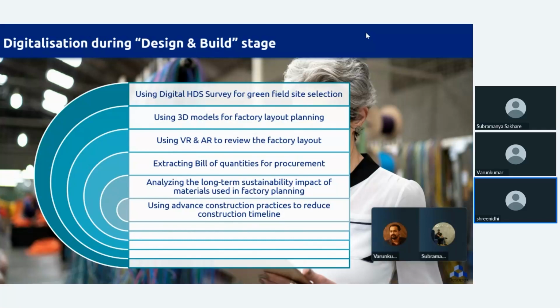By this, what happens is that sometimes we unnecessarily have to excavate to find a lowest point for water draining, or do some waste management or something like that. But what if the site already has a point where you can strategically plan in such a way that it can be utilized? So for all such scenarios, what is required is a high definition survey with the 3D terrain data coming from that. You could use a drone, or you could use laser scanners for that matter, which can bring in that information for your designing team.